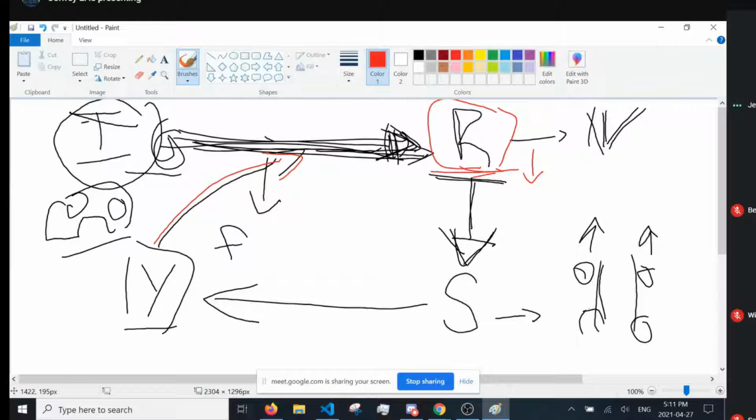We're still only able to change the voltage of the robot, right? We're still not able to directly just magically set a speed on each of the wheels. The internal logic itself is able to receive a desired speed as an input and bring us to that point, and that is the whole theory of control, right? So I'll clear this up a bit.